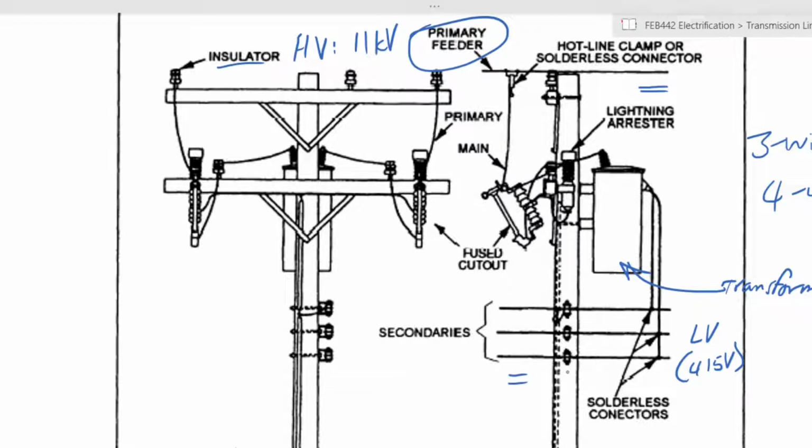And this is one thing that you will note with electrical poles. Sometimes, in fact, you will find, since the infrastructure already exists, other services will make use of the same poles that are constructed by distribution companies such as Kenya Power. So you'll find things like fiber internet cables or telephone wires also mounted on the same poles. But in order to do that, they will usually be mounted at an even lower level. So it goes, the highest voltages are at the top and you go downwards in order of decreasing voltage level.